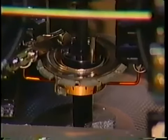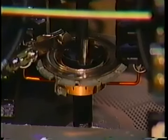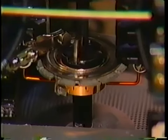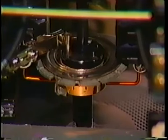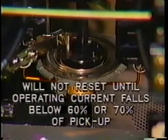Once the disk is rotating under fault conditions, inertia will cause the disk to continue slight movement, even if the current falls below pickup value. This overtravel could cause inadvertent tripping. Moreover, the disk will not reset immediately. In some relays, not until the operating current falls below about 60 or 70% of pickup.